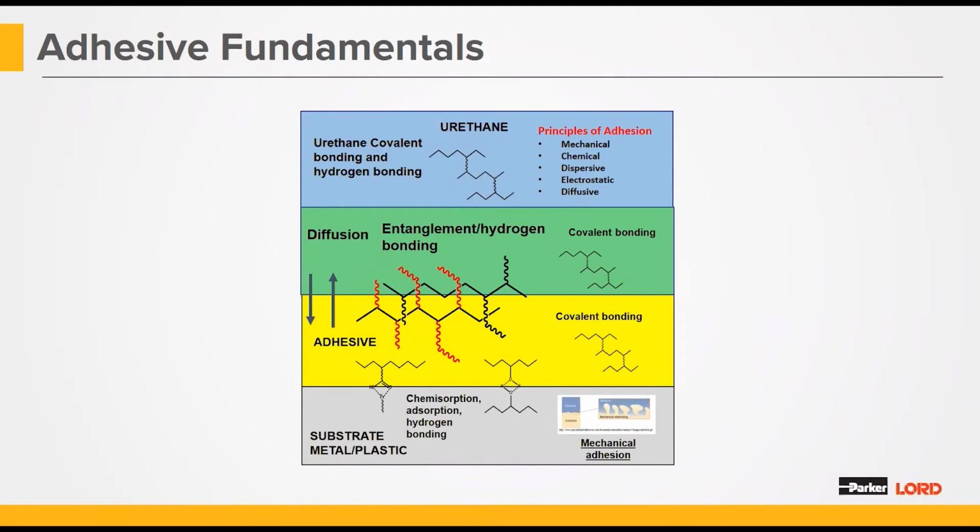So while all this is going on in the body of the urethane during the cure process, you start to get covalent bonding. And then in the post-cure, what you have is an alignment of the hard blocks in the polyurethane, and you get hydrogen bonding, and it rounds out your properties.